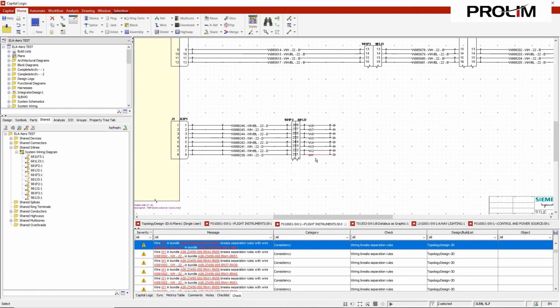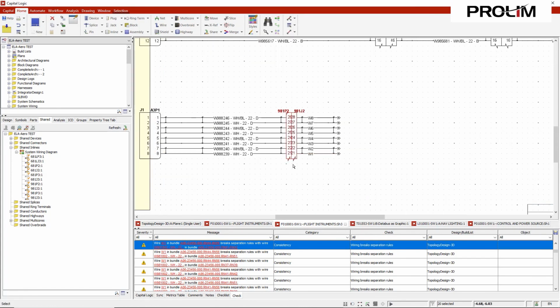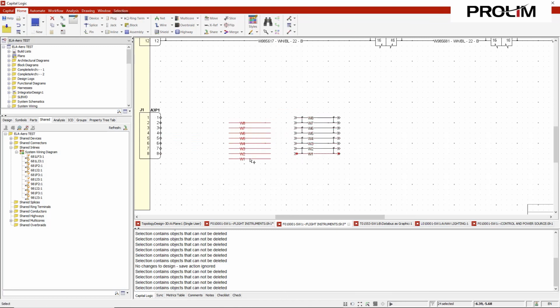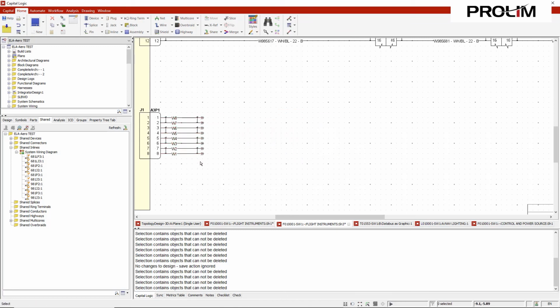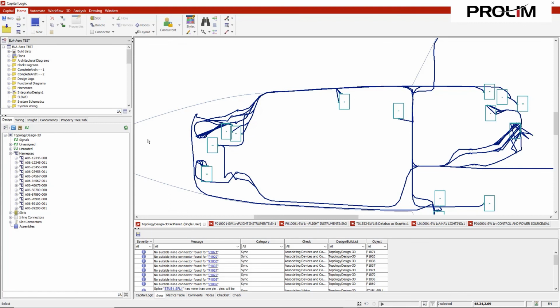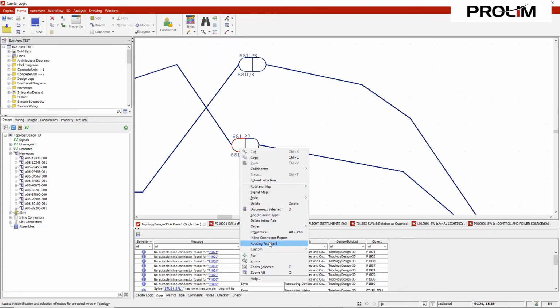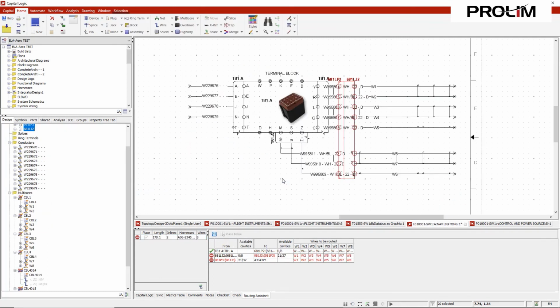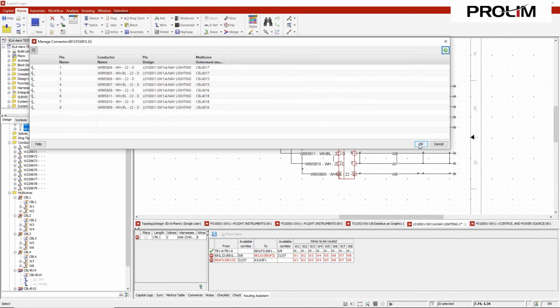And then we can go through the same exercise that we did within the last demonstration, and we can actually use the routing assistant within Capital to quickly see what other paths are available and if there's better paths available for this. So we've gone and updated it so it's no longer going through that other pathway through that other inline. We can quickly route it through this 681 inline here.